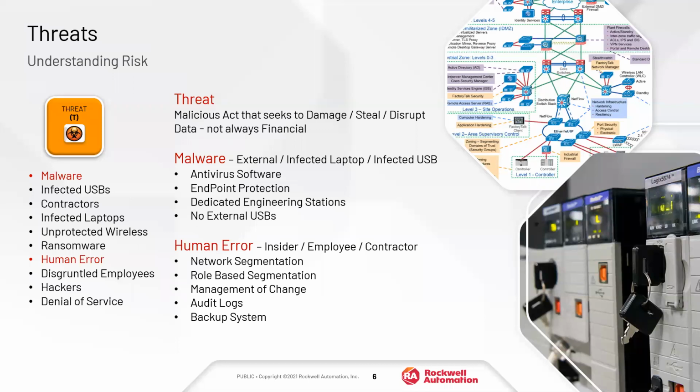From what location are they changing that set point? And not only knowing that it happened, but also knowing what operator, what maintenance person, and what terminal are they using. So an example here is we typically look at FactoryTalk AssetCentre on the Rockwell side. It allows backup of all the controller configuration files, but it also provides an audit log for all the system changes, including the HMI, the PanelViews, the controllers through Studio 5000.